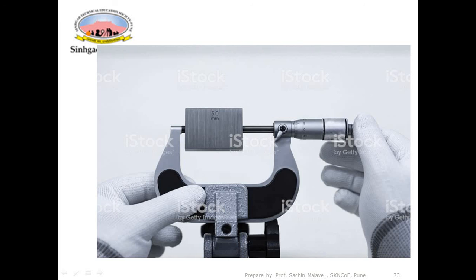Like a screw cutting. So there has to be, this relation is fixed. If the thimble rotates through one complete revolution, then the spindle will advance by some distance. It will move in axial distance through some distance. So that relation has to be constant every time. If this relation is not maintained, then there is a possibility of what is called a backlash error.